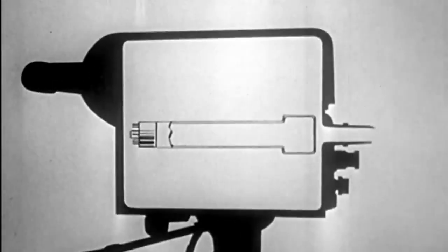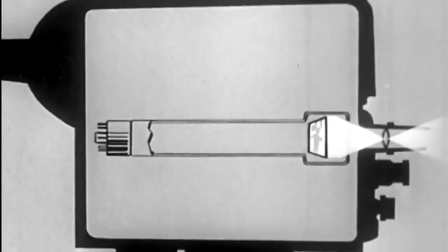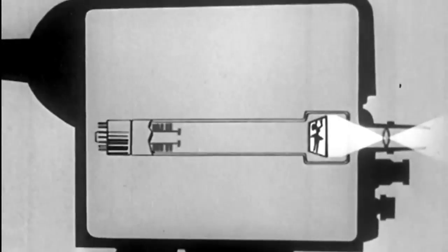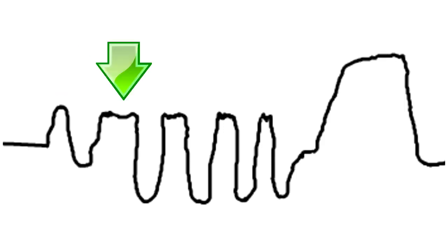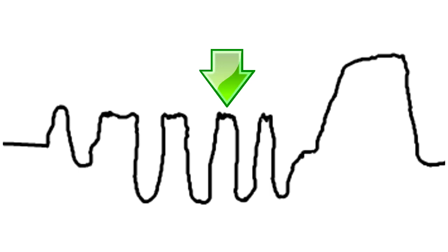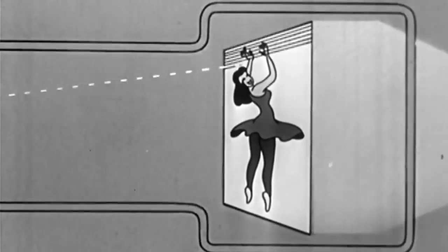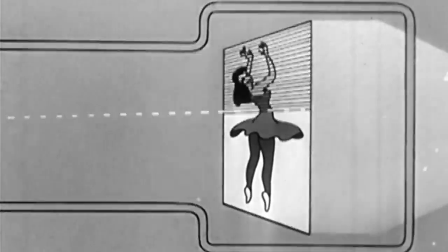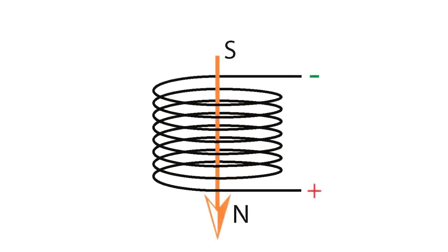How much time it takes for the flyback depends on the scanning circuit, but a typical vertical retrace time is 5 lines. Once the scanning spot retraces from the bottom to the top of the raster, 5 complete horizontal lines are produced. This vertical retrace can be completed easily during the vertical blanking time, with 4 lines blanked at the base before flyback and 5 lines blanked during flyback. 12 lines remain out of a total of 21 during vertical blanking. These 12 blank lines are at the top of the raster on the downward vertical trace.